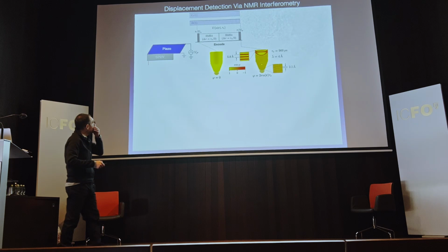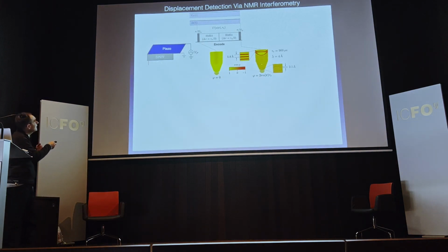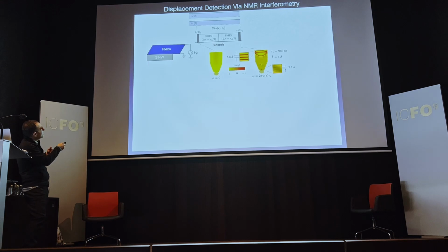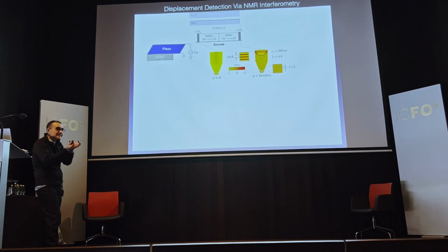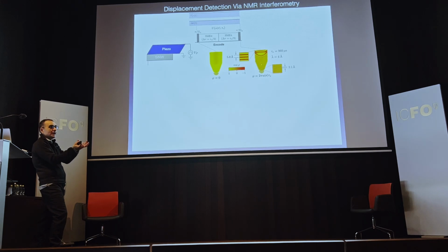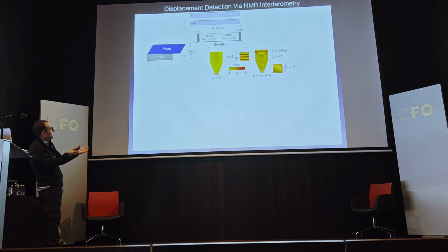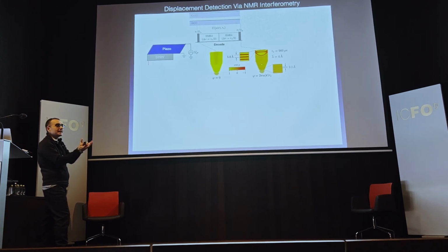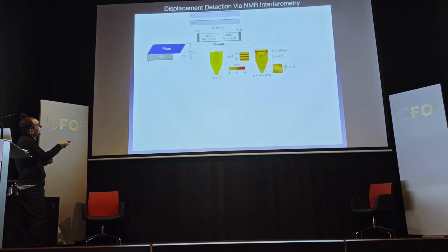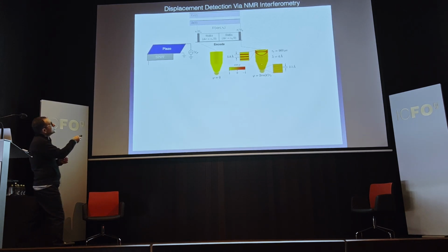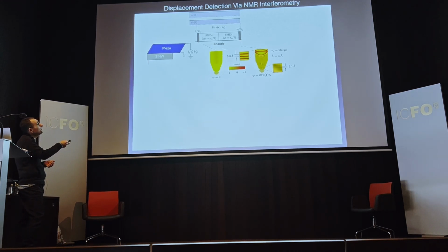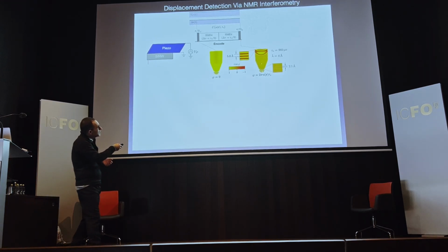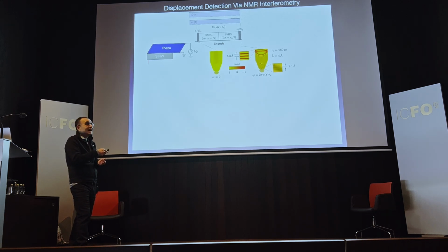We decided to have some fun with this. So the sample, our silicon nanowire sample chip, is mounted on a small piezo. And so you can physically move the tip relative to the gradient source. So what we did was we applied a voltage to the piezo, and it moved the nanowire by something like an angstrom. We start from a uniform state, and then we use these SME4 sequences to apply a very, very high pitch. I don't know if you can see it, but you see this moire pattern. That is because there's a very high spatial periodicity that we've imprinted in the z-axis magnetization.